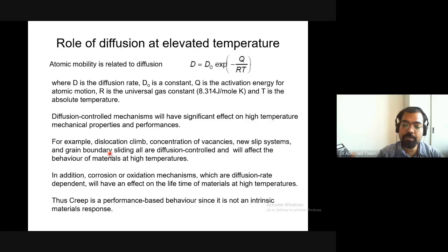Usually you put chromium in steels because chromium has a higher Pilling-Bedworth ratio, which is simply the ratio of its oxide volume to the volume of the non-oxide form, so just chromium, which is greater than 1. So you put chromium in steel because, first of all, chromium has a higher affinity for oxygen. So chromium will be forming chromium oxide,